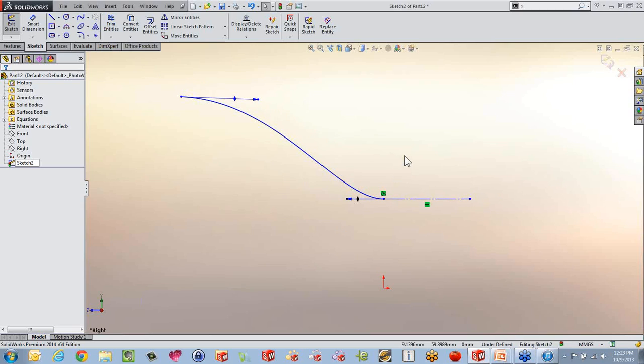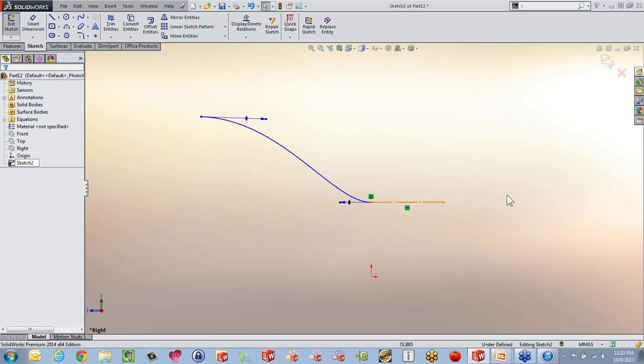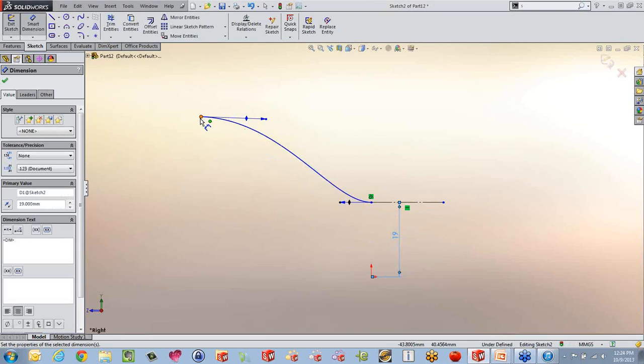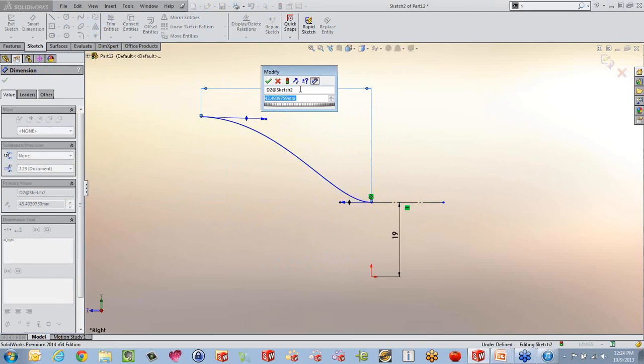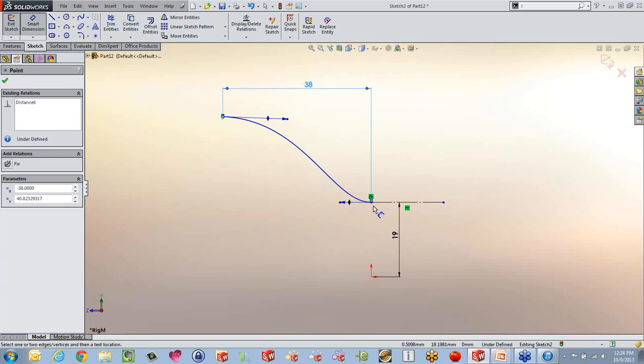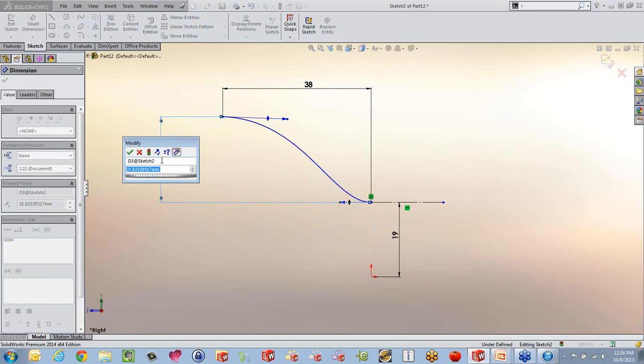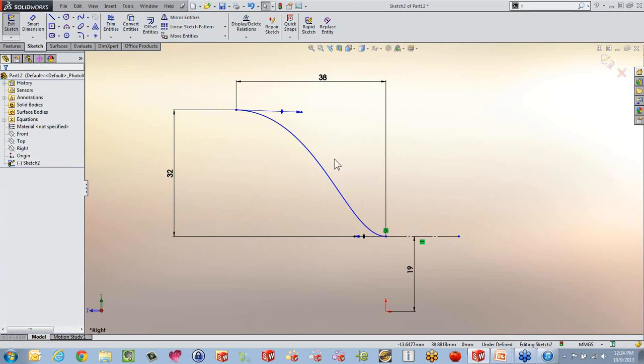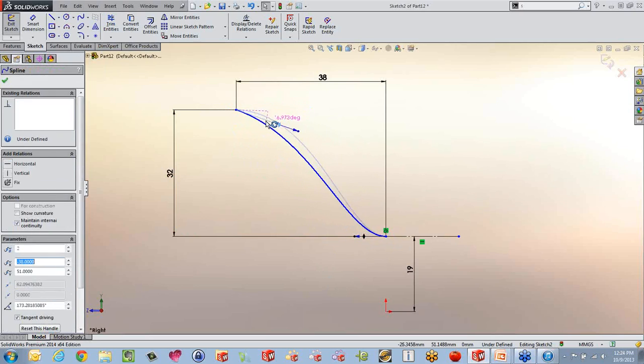And you can also do that for surfacing. So let me finish putting some dimensions on this part. What I'm really trying to do is make a sweep, and I'm trying to create some guides for my sweep here. So I'm just going to give this a couple of dimensions, just to make my life easier when it comes to defining these. Make this one here and this one 32. So I sketched this one on the right plane. There's not really any specific voodoo about this spline, other than that at this point we have these different dimensions. We have made it tangent down there, and we now have control of the spline like this.